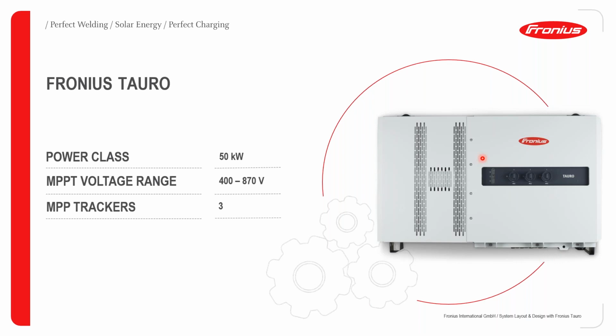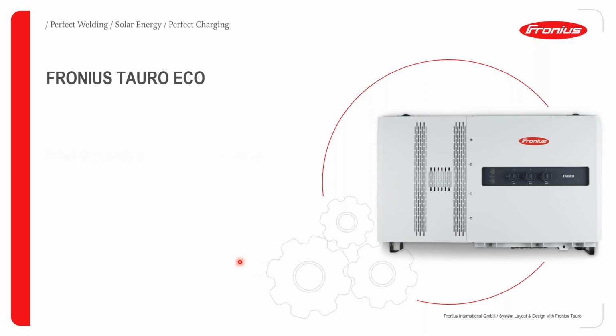This inverter will have up to 3 MPPTs inbuilt, and in terms of current handling capacities for the 3 MPPTs, we can see that we are starting with the MPPT 1 and 2 taking 36 amps each, and MPPT 3 can take a maximum of 72 amperes.